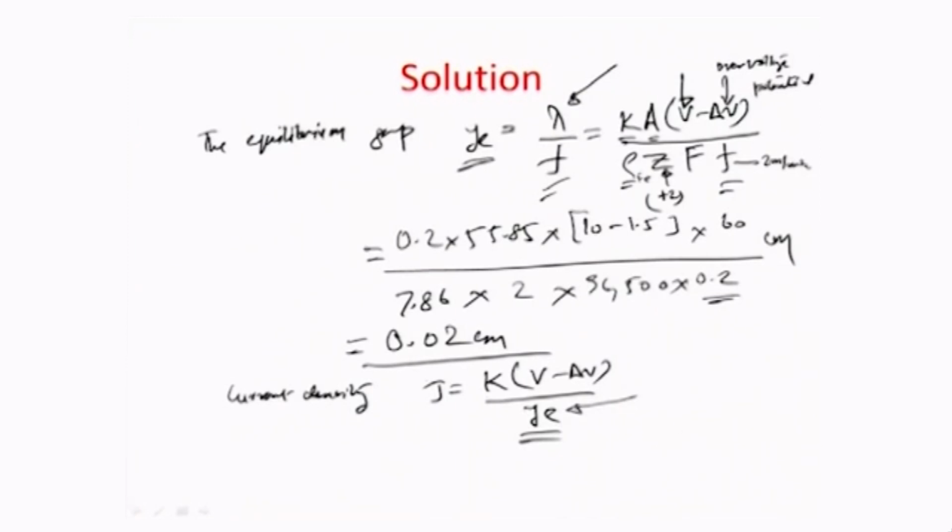Okay. So, the current density is actually conductivity times the field, the total voltage which is available after taking care of all the different anodic overpotentials due to migration effect, all those things together, as we illustrated before, is delta V. So, effectively the available voltage between the two electrodes which can do machining is V minus delta V, and so the current density, which is the ionic transport between the two electrodes, is equal to the conductivity times this available voltage per unit equilibrium gap Y, which is there between the tool and the electrode.